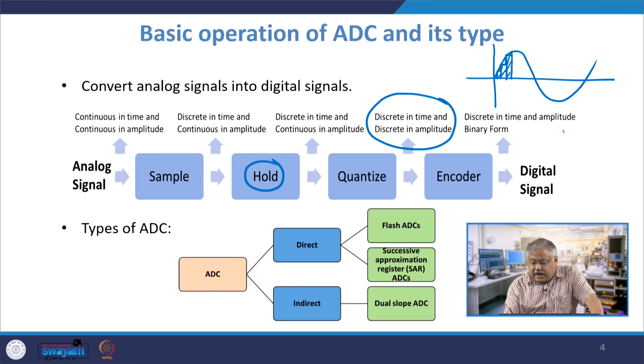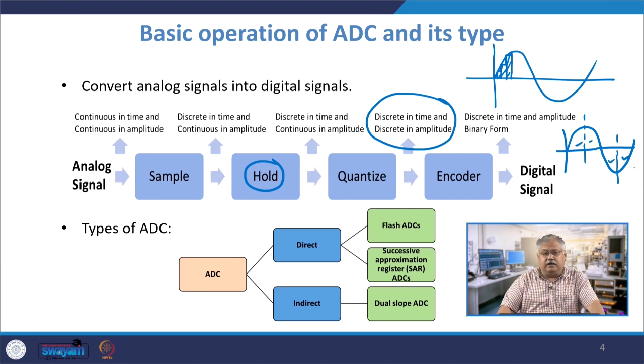It is very simple and straightforward to give you an idea about. Say I have a signal like this, right. I divide it, so there are 1, 2, 3, 4 sections available. Now I can show, in very layman language, what we mean by quantization. Now if you want to quantize this into 3 bits, then 2 to the power 3, there will be 8 such available states, starting from 000 to 111, right.